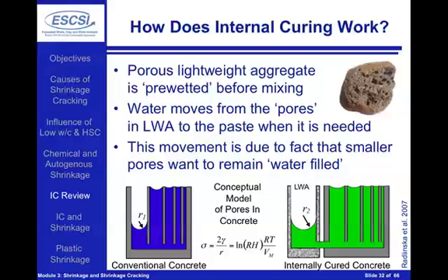The biggest pore is emptied first. So if we can place something that has water inside of it with bigger pores, water will preferentially leave the lightweight aggregate and keep the paste filled. The interesting part about this is that the water comes out of the lightweight aggregate at exactly the right time.